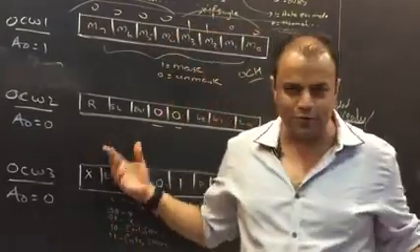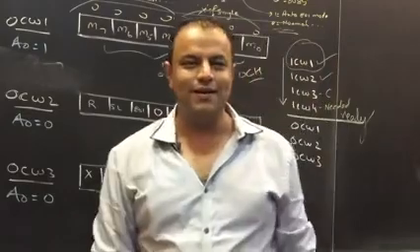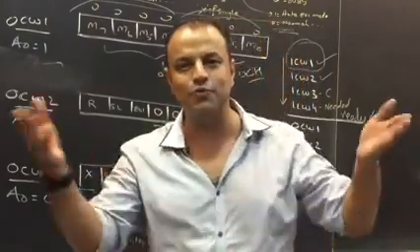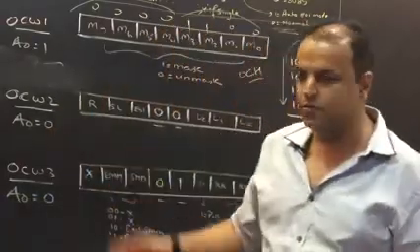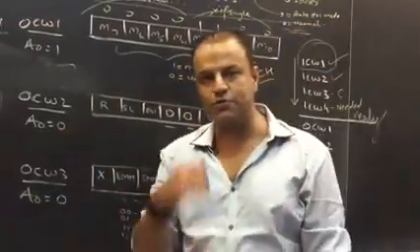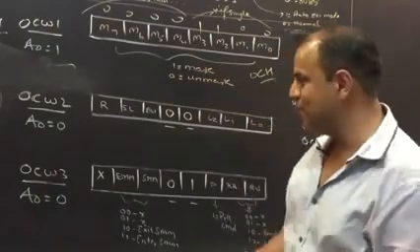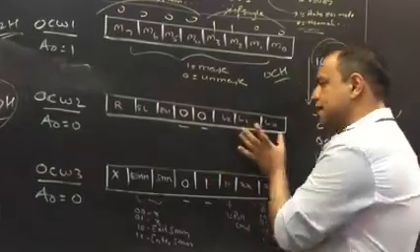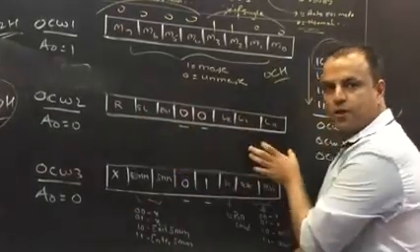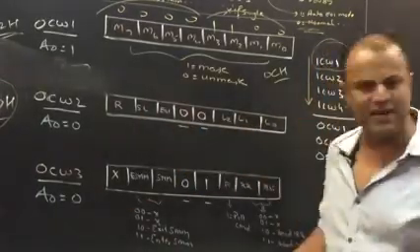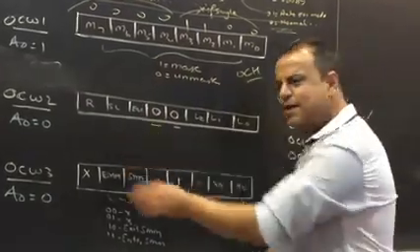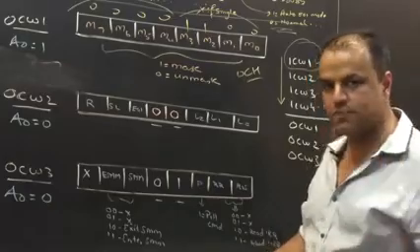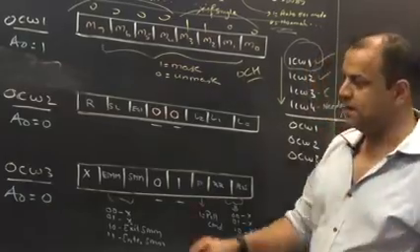It will take me half an hour to explain to you the meaning of each one of them. And as I said, I'll be using your energy at a place where it will never actually be useful to you in the exam. This is what you really need. You don't need this. If you still want to know this, I'll give you a short audio of it. It's really not required, not from a student point of view. Anyway, so there are 8 options that you choose over here and this is the line number. So you choose what option you want and you program the line as per your desired option. I gave you one simple example, set priority command and give the line number. Whatever line number you tell over here will automatically become the lowest priority. Are you clear? Not the highest, the lowest.